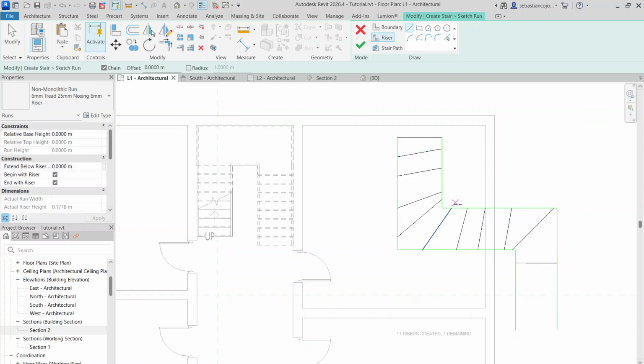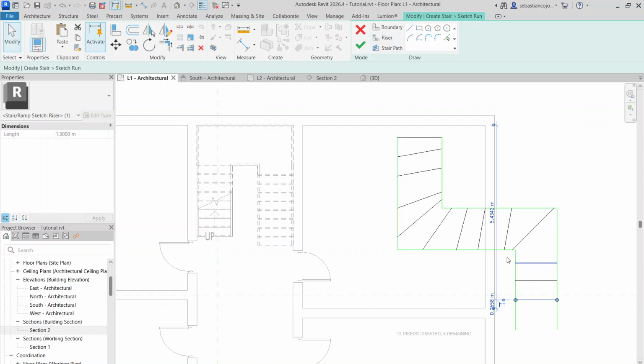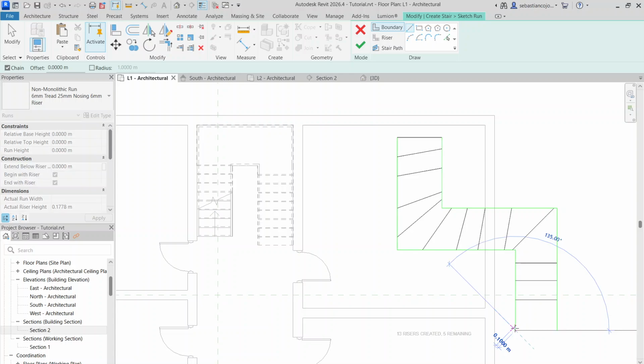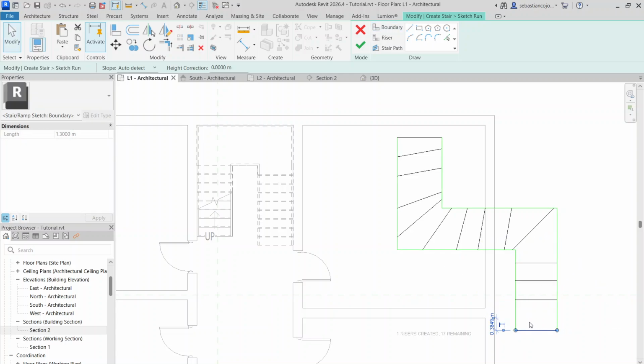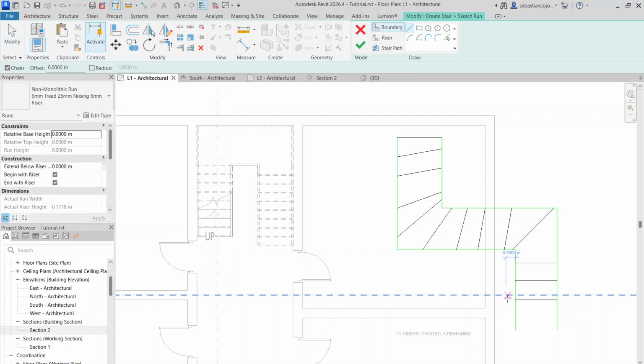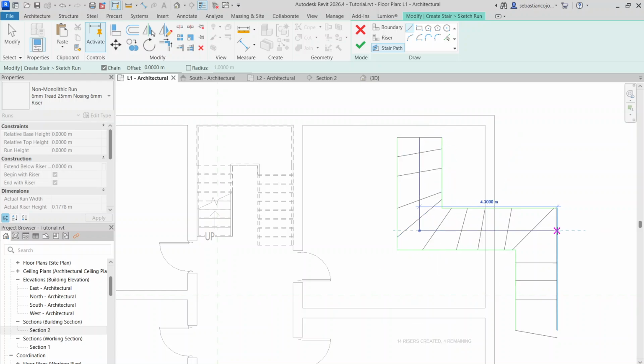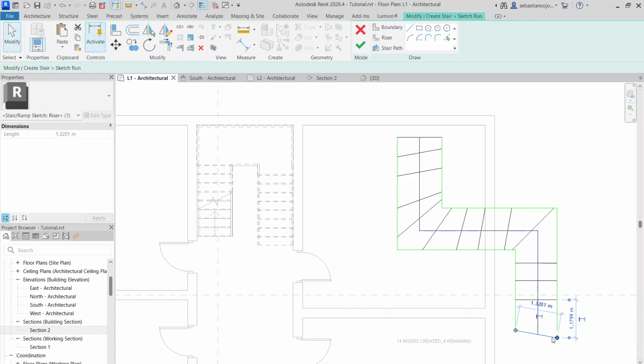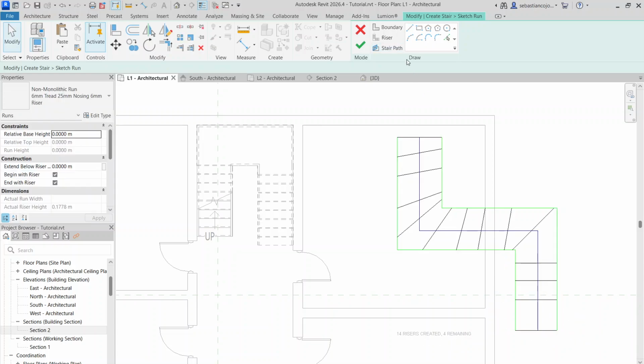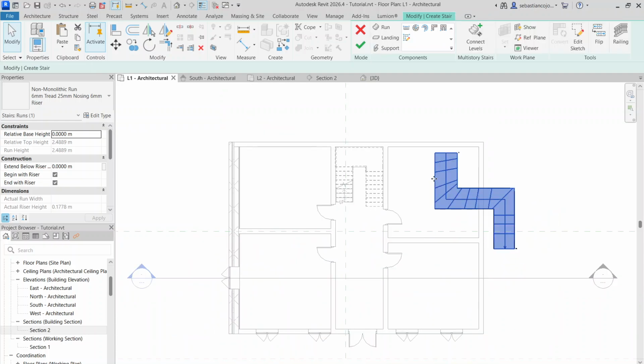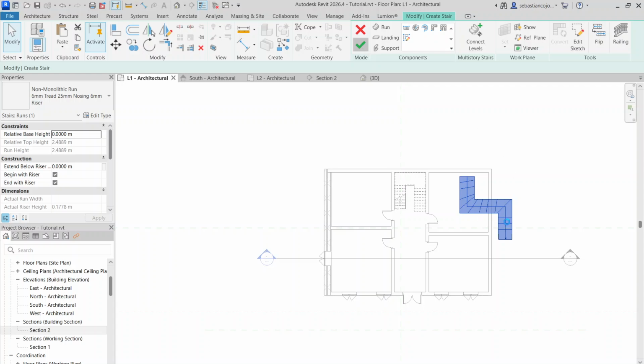So you basically do the railings of the stair, and now you do the treads of the stairs, and you need to do them in sequential order. If you do not do it in sequential order, it will mess up your job and you won't be able to create the stair. So you create the riser, the tread, and now you draw the stair path from where you started with the first riser, and you go something like this supposedly, and this should be it. It will look weird, but now you have a new stair. I don't know how it even looks on the outside, it's so weird.